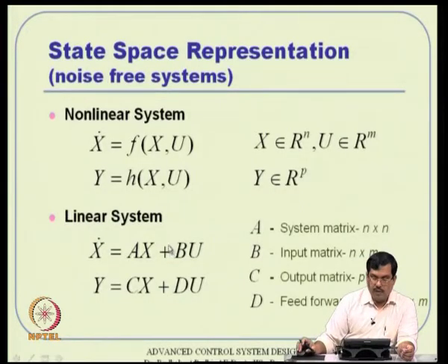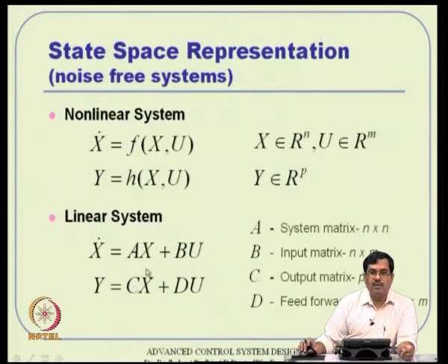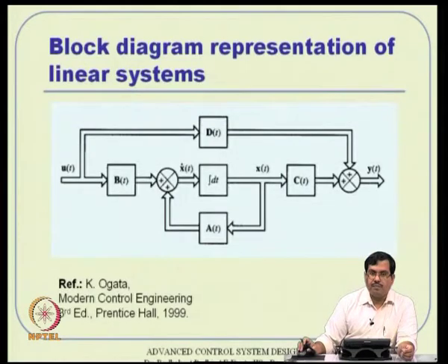Okay. Now, if I consider y equal to Cx plus Du, I will pass x through a C matrix, which gives me Cx here, and then I will pass this u through the D matrix. So, that gives me a Cx plus Du representation here. And in general, remember these matrices A, B, C, D are all time dependent. That is why you see time varying notation here.